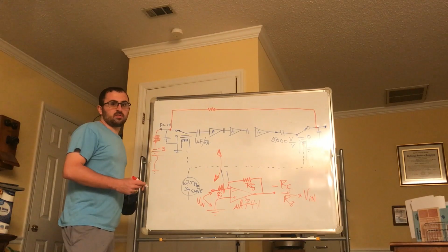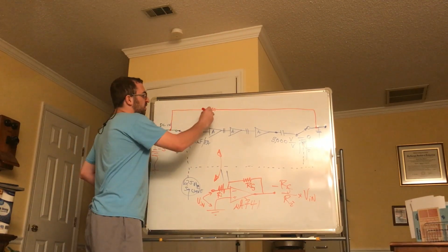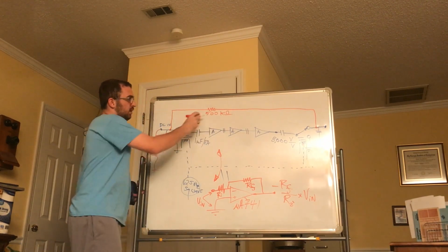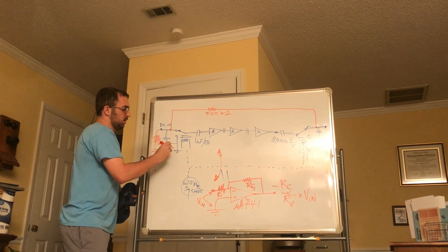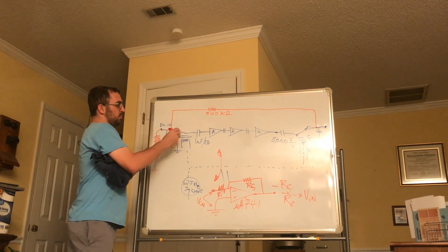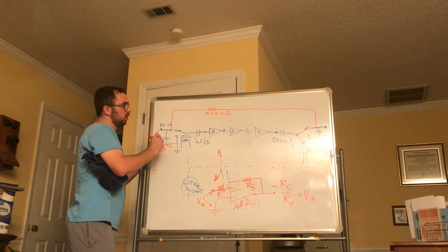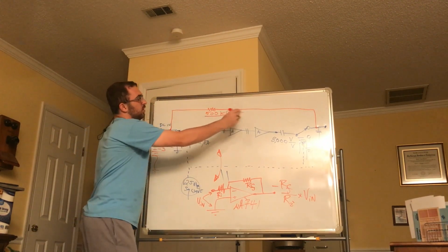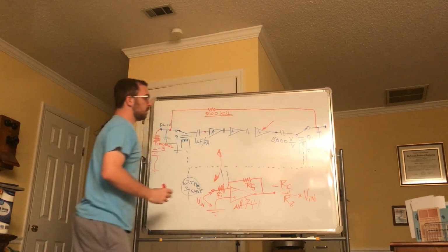Okay, so we want an amplifier with a gain of 5, not 8,000. So we can set this guy equal to 500 kilo ohms right here, and this guy would be 100 kilo ohms. So it matches the impedance well. The 1 meg that this tube has is large in comparison to that, and that's our goal. So most of the signal gets there, and then this 500K is very large compared with the 35 kilo ohm output of this amplifier.